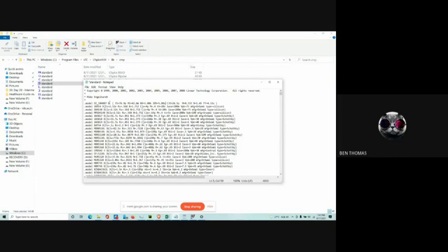This capital D is really important. This capital D is what makes LTSpice recognize it as a diode. You have to save it, right? Yeah, we have to save it.